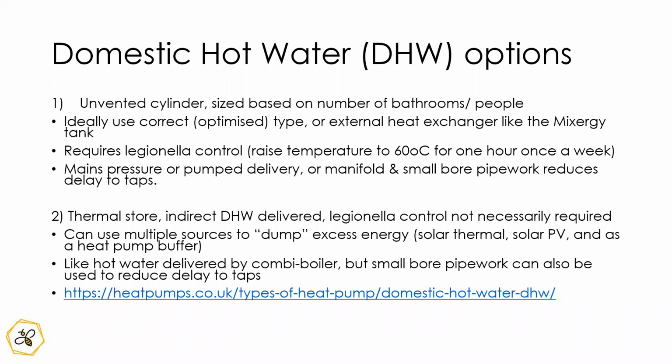The pressure that you get from your hot water cylinder is either just below mains pressure, because that's the mains pressure your water comes in at, or you can boost that with pump delivery. The second option is to have a thermal store, and whether you go for one or the other will be very different.